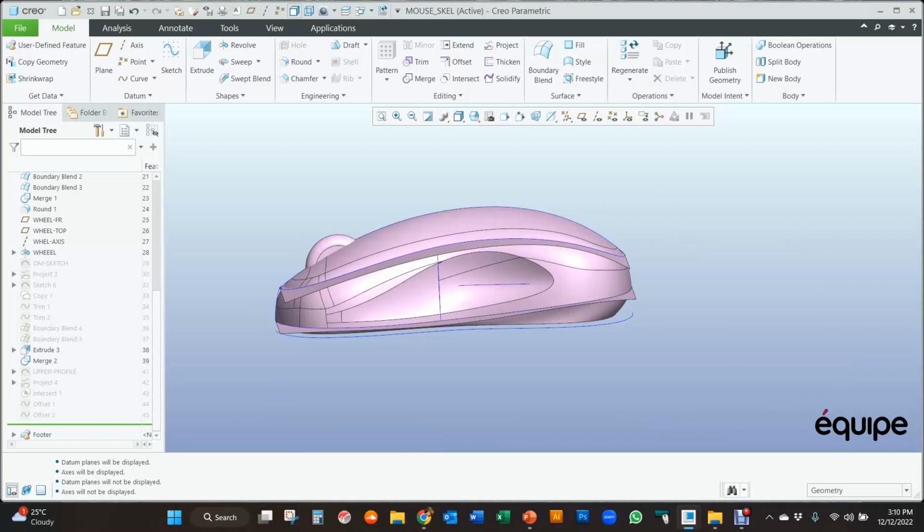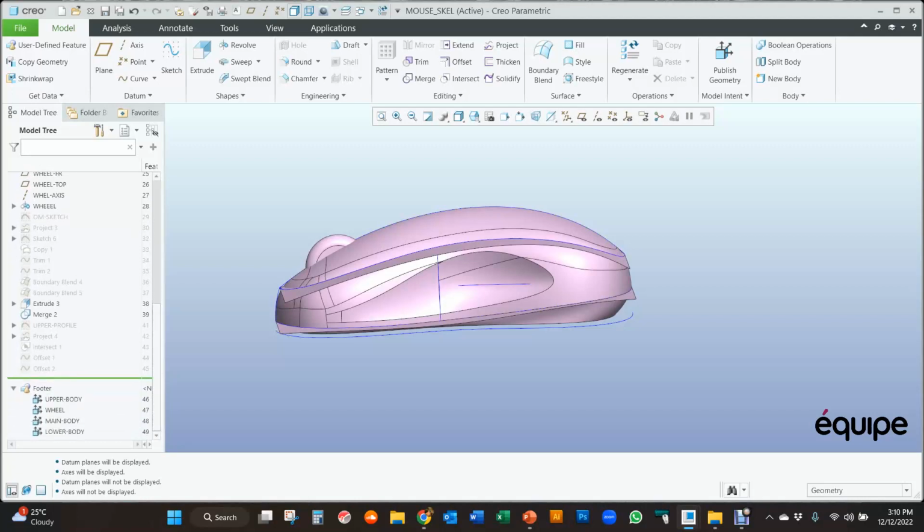Certainly, it's good to start with your skeleton model and then filter the references down into the parts. But it's a sort of backwards and forwards, a continual process of updating your skeleton and filtering those references down to your parts. As your design develops, you'll be going back to your skeleton, then back to your parts. The way we do that is through these published geometries.